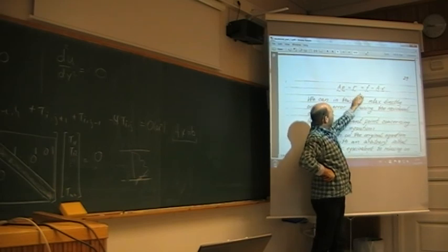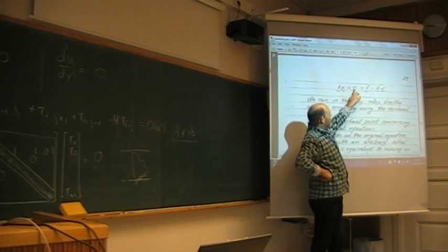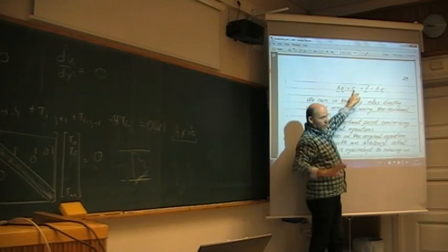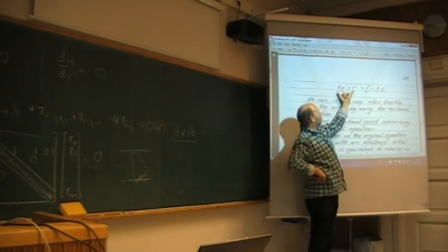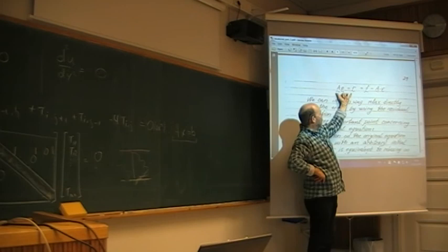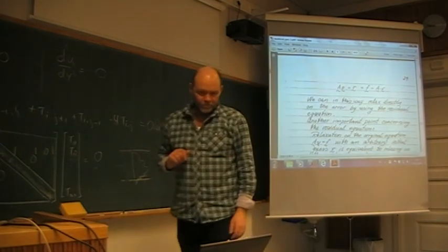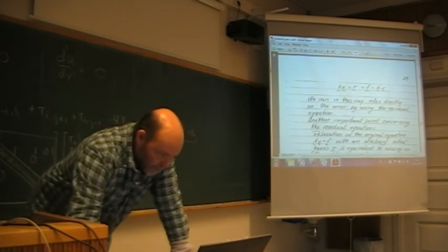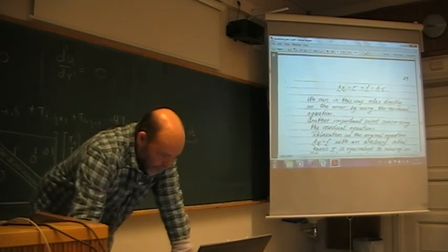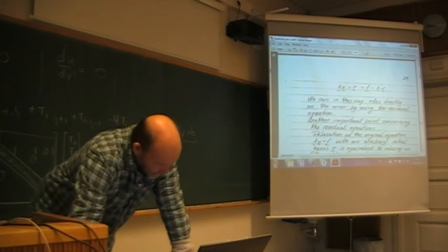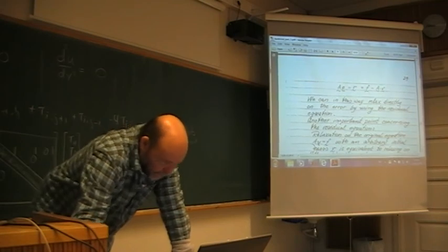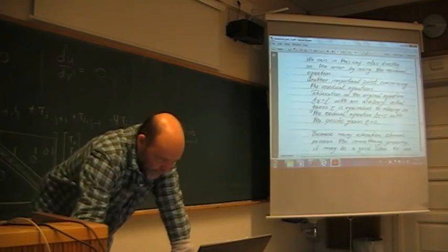If it's not, then you take this residual and you move it to a coarser grid, and then you try to solve this equation for the error on the coarse mesh. And when you find the error, you update your velocity or your unknown, hopefully finding a better one.